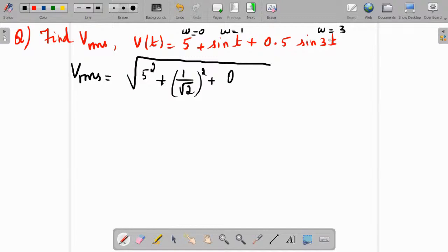Next, find the average voltage. Okay, these three questions are different, unique-style questions, so note them carefully. Here for average voltage, this kind of formula applies to either question number 2 or question number 4. Okay, check for DC component. If they ask for average voltage for a sinusoidal series, it can be sin or cos: sin t plus sin 3t.